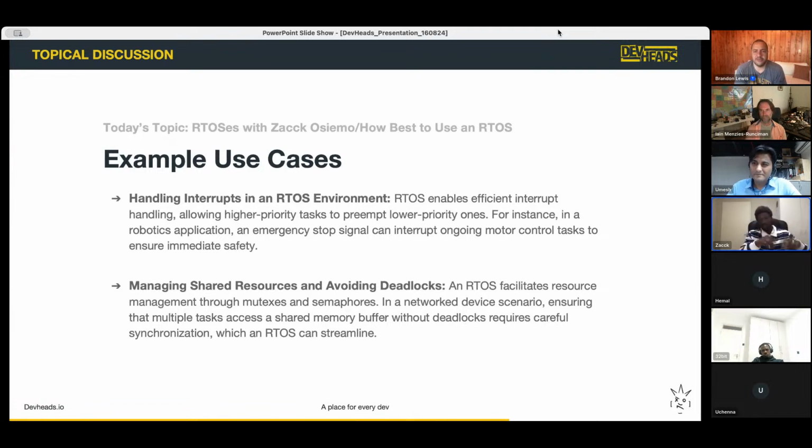Let's call them functions, because threads are functions here. In mutual exclusion, only one of those would be able to use that screen at a time. And that's what a mutex is. RTOSs come with these structures inbuilt so that you can just start using them. You don't have to build a mutex yourself like in bare metal.